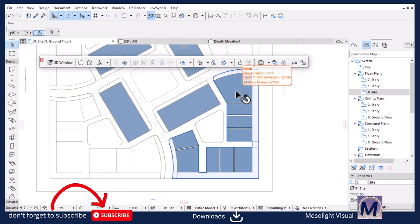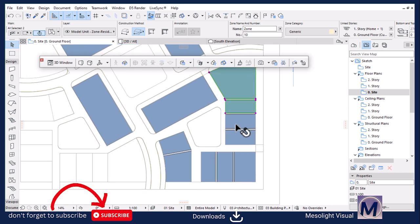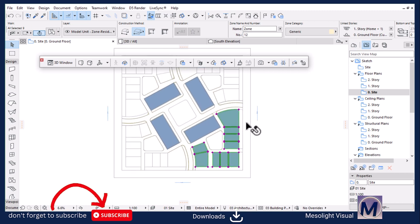What I'm going to do is select all of them like that. Tab this, and then hold Shift to add another one. Tab, hold Shift to add this. Tab, and then hold Shift to add another one. That's the whole trick to select elements like this. Tab, and then hold Shift to pick the other one. Just like that. Hold Shift to add the other one. So now I have selected all the residential zones.